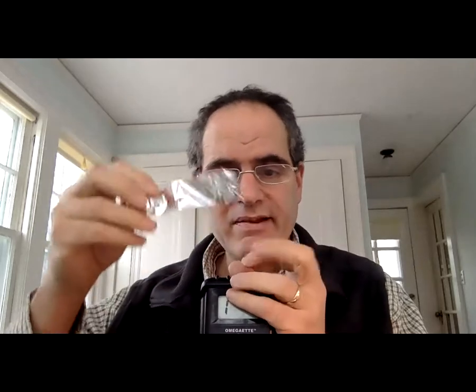What I have here is just a digital voltmeter, much like the ones that you've been sent. Right now it's set to measure electrical resistance, on the 200 ohm scale. Here's a piece of aluminum foil. As you can imagine, aluminum is a very good conductor. It's one of the materials that has the highest conductivity. If I connect the probes to the aluminum, you should see that the resistance is very low, on the order of a few tenths of an ohm across this strip of metal. Nothing could be simpler, right?